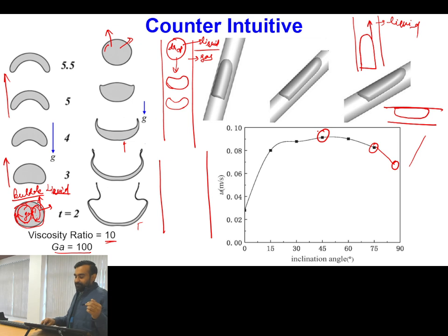So typically, whenever a bubble moves, buoyancy force is responsible for the rise of the bubble. But there is one more force which is balancing the buoyancy force so that the bubble remains at a constant velocity, and that force is actually drag force. Buoyancy is because of gravity. So the bubble is lighter and it is rising. Okay. But what other force will be coming into the picture? Drag force. Okay, drag, because see, when this bubble is rising in the upward direction, what is happening?